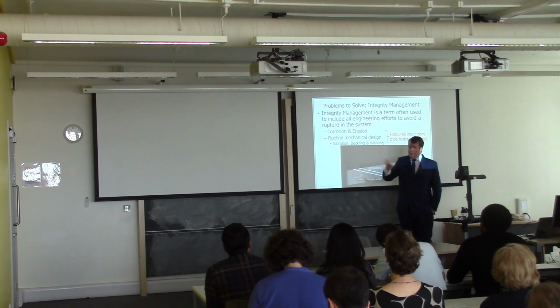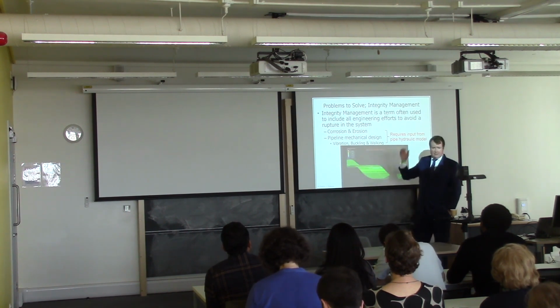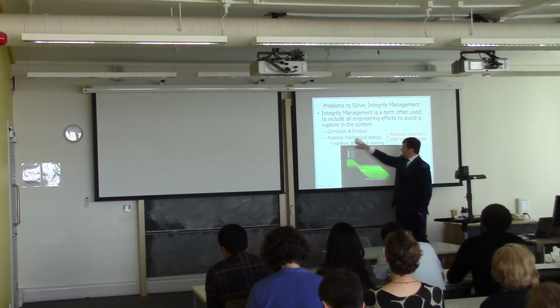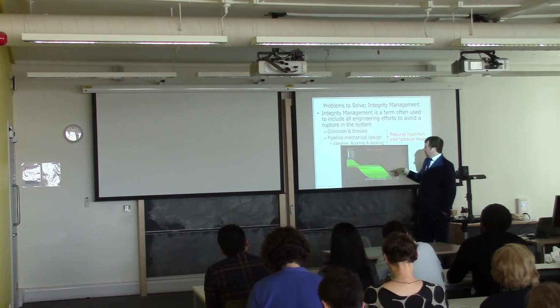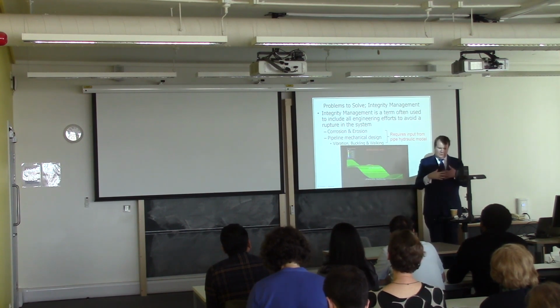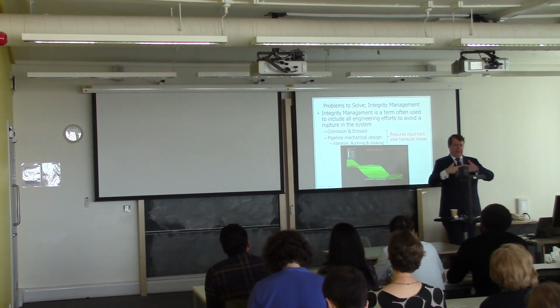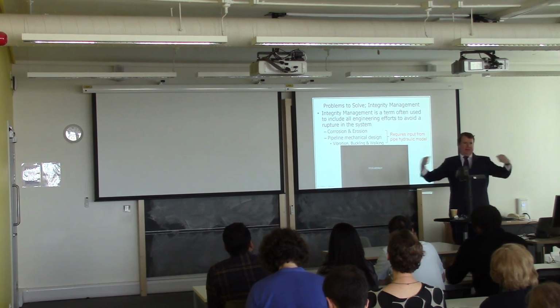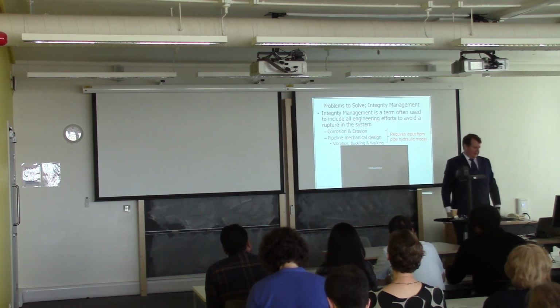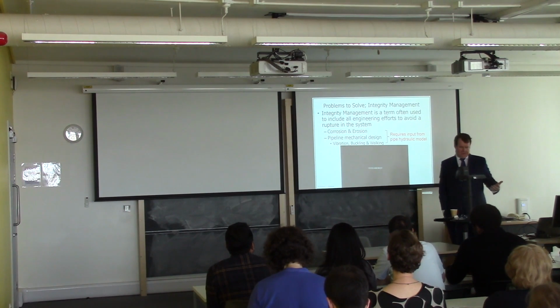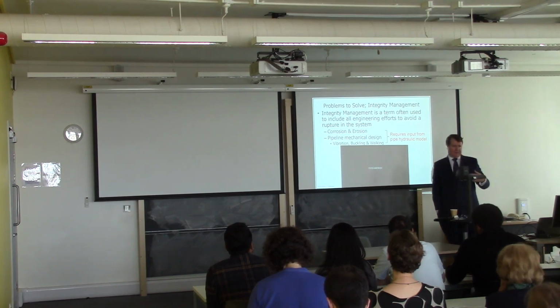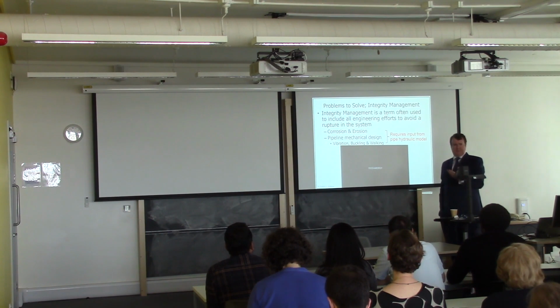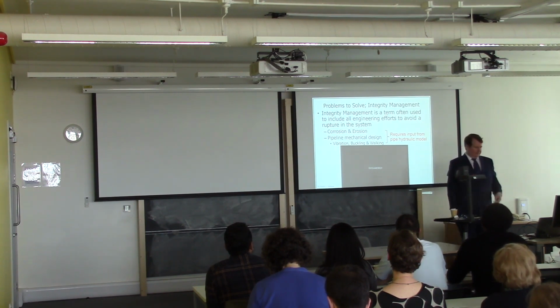Erosion, this is flow wearing down the pipe, but also some pipeline mechanical issues, which are shown in some of these videos here, caused by the pipeline warming up and the metal expanding, it can pop out of the ground, and then as it cools it contracts, keeps doing that and causes all kinds of stresses on the pipelines. So flow assurance guys don't usually get involved in doing those calculations, but we do get involved in giving them temperatures and pressures and compositional information for their calculations.